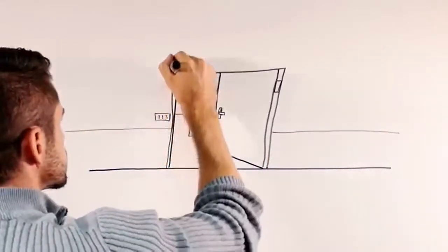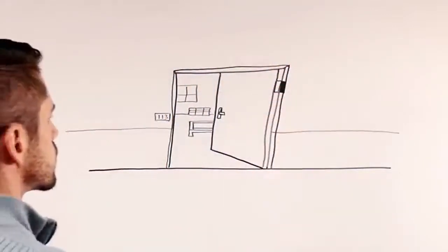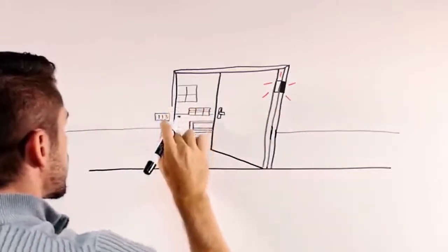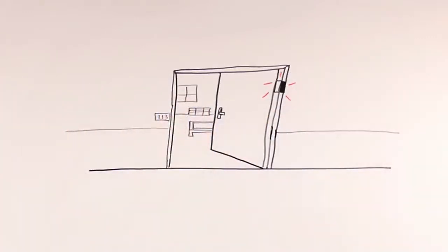By the way, fire doors are usually rated for a shorter time than the walls around them because the amount of combustible material near an operable door would be lower than a wall where furniture and stored items could create a higher fuel load.